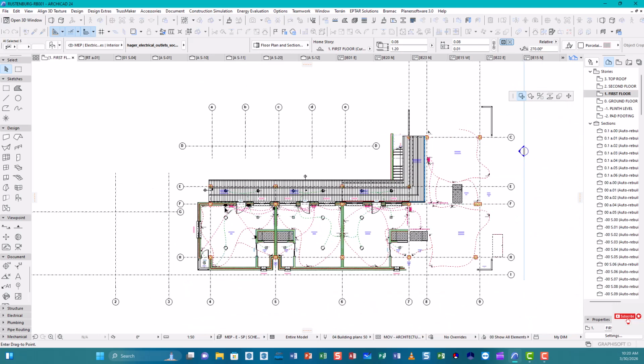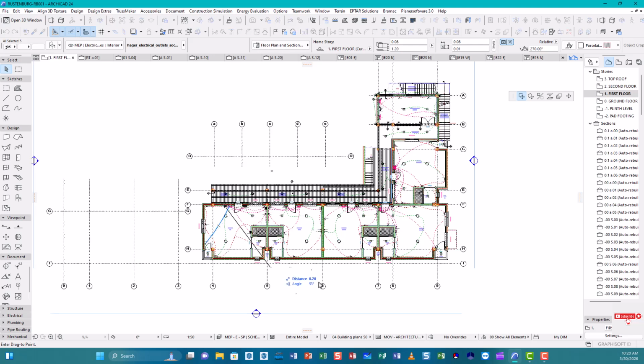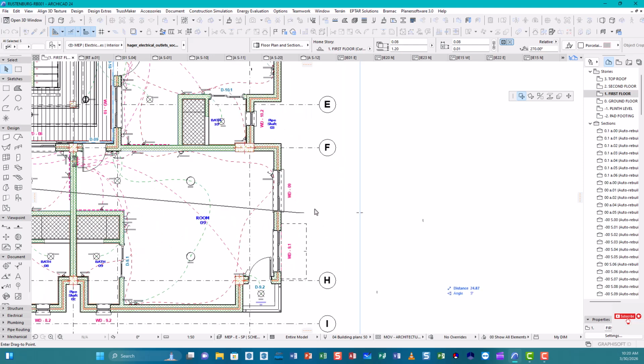So I'm going to zoom out and drag the plan to the left, come right here, because I know that these walls are symmetrical and parallel. The ones on the first floor are collinear with the second floor. So I'm just going to press Control to create a copy. I'm going to copy them right there and leave them there.